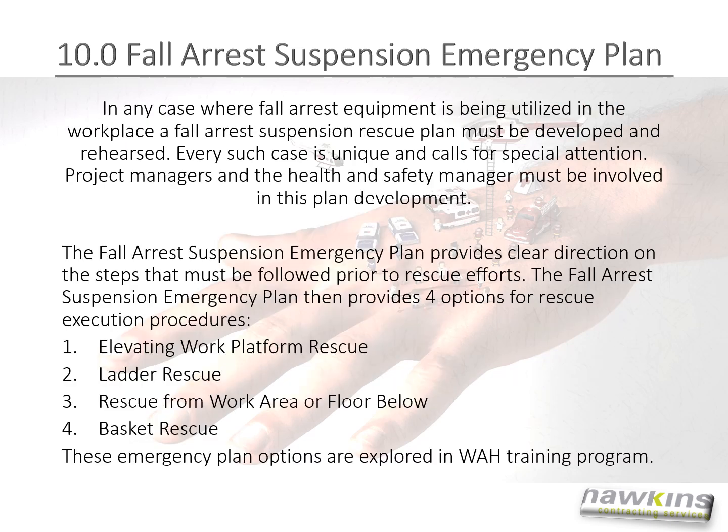In any case where fall arrest equipment is being utilized in the workplace, a fall arrest suspension rescue plan must be developed and rehearsed. Every such case is unique and calls for special attention. Project managers and the health and safety manager must be involved in this plan development. The fall arrest suspension emergency plan provides clear direction on the steps that must be followed prior to rescue efforts.